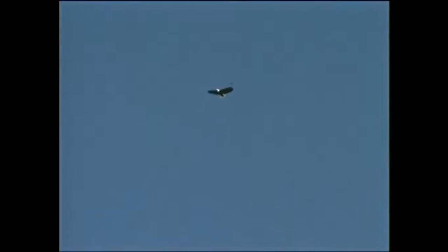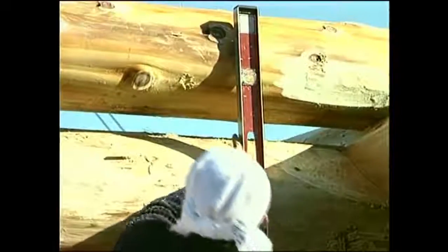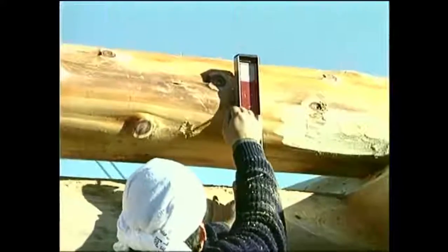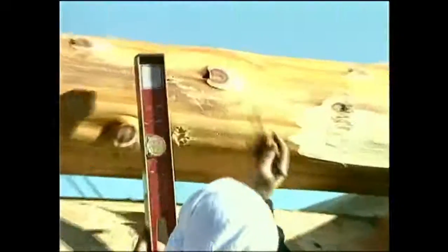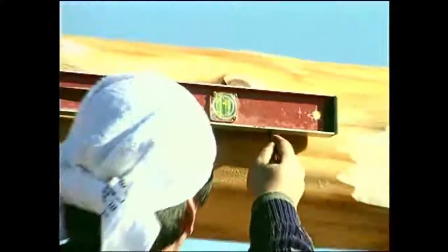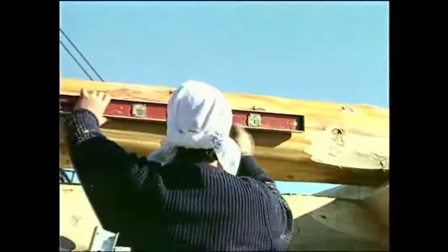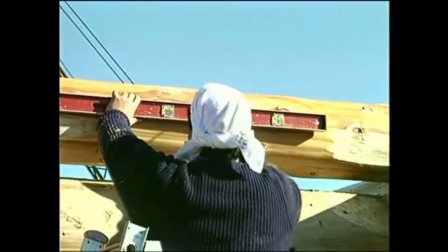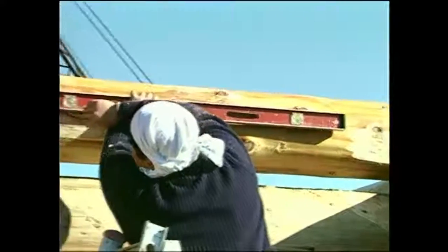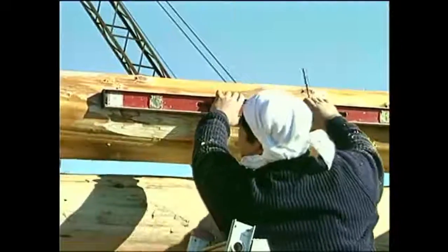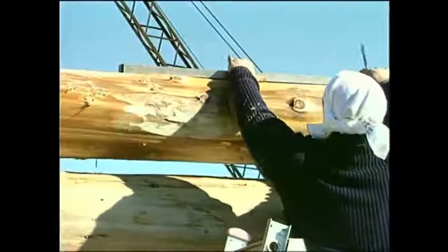Mark the exact cut width onto the header log. Then extend the height measurement that you have already located to intersect this mark. Use your level to draw this height to the other side of the window, or better yet, snap a line at the header height after you have measured in the exact window width.